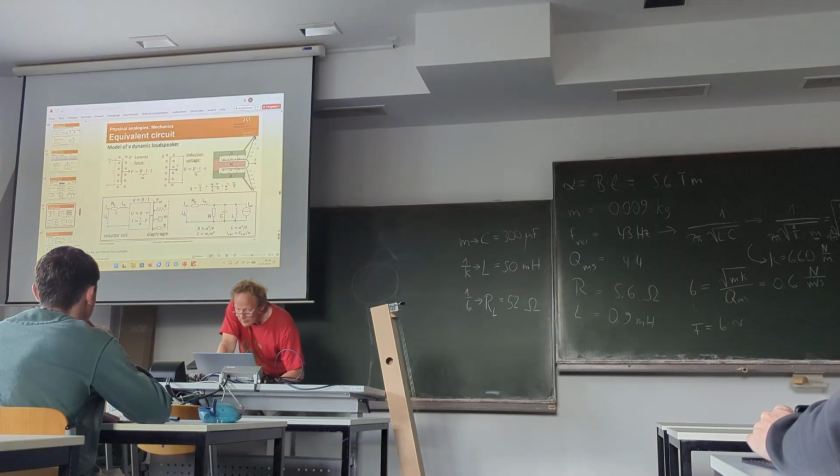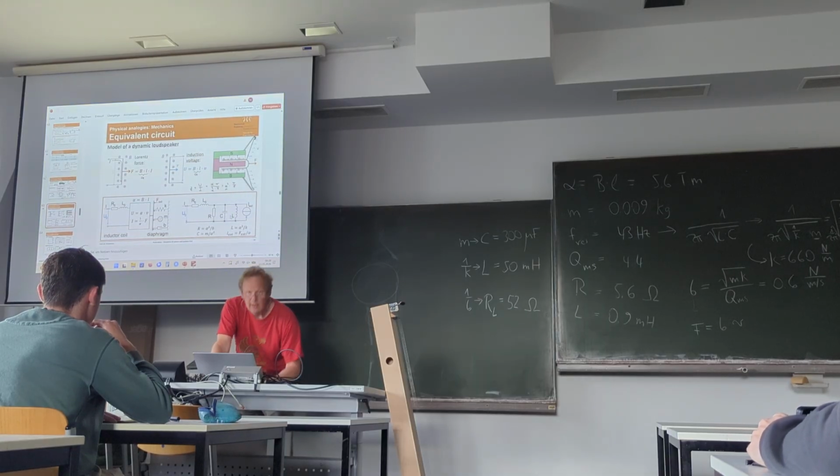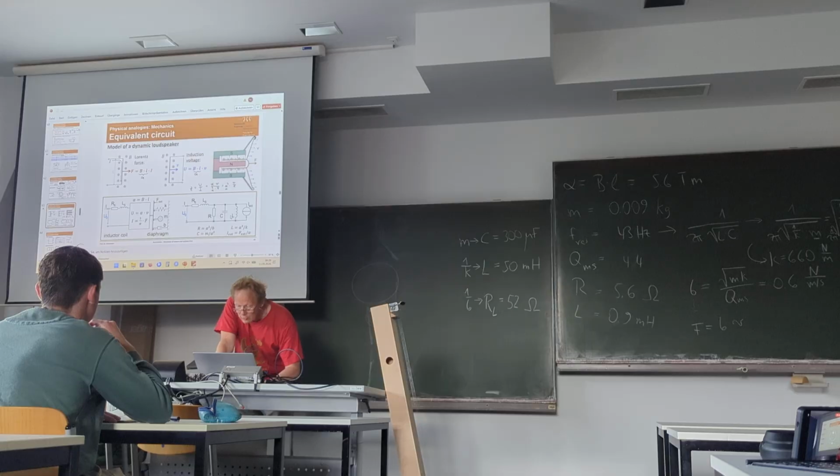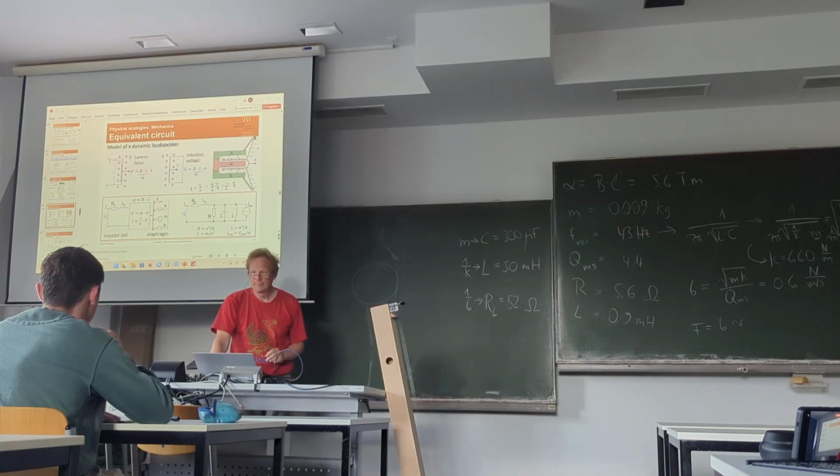And well, that means when we have a resonance, and C and L are, let's say, cancelled out, and only this large resistor remains, then we could really measure here the sum of R_S, okay, probably also a little bit of effect of L_S, and R. And it means, yeah, approximately 60 real ohms, not just 5 ohms.